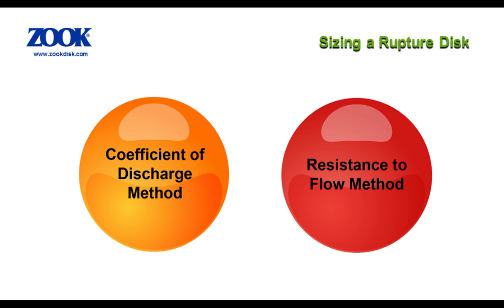Cam mentioned earlier an application that includes a rupture disk device in combination or in series with a pressure relief valve. For this application, the sizing is based on the pressure relief valve, and the effects of the upstream rupture disk device are accounted for by applying a default 0.9 combination capacity factor, or CCF, to the sizing calculation to make the appropriate changes to the rated relieving capacity of the combination. The default 0.9 CCF value can be used for any combination of rupture disk device and pressure relief valve.